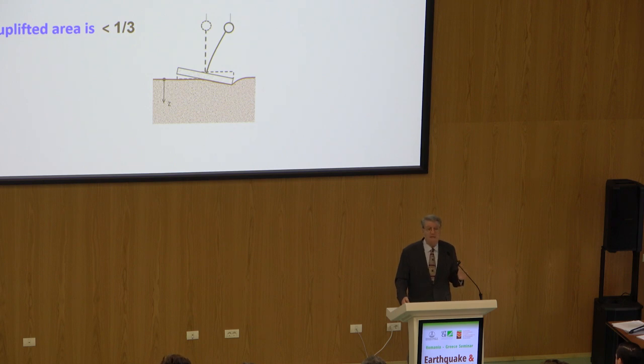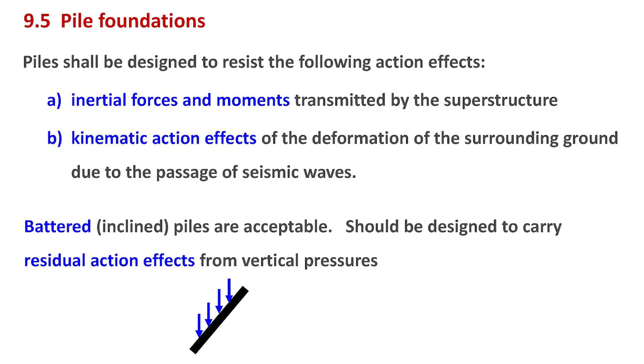But in force-based design, things are very strict. Only 1/3 of the area of the foundation should be uplifted, meaning an eccentricity, a dynamic eccentricity, of about 1/6 of the base. And the pile foundation is the same thing.